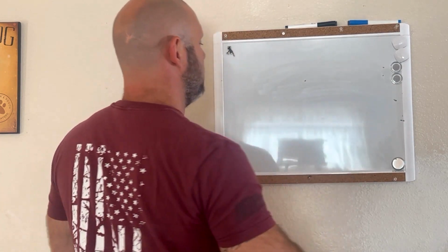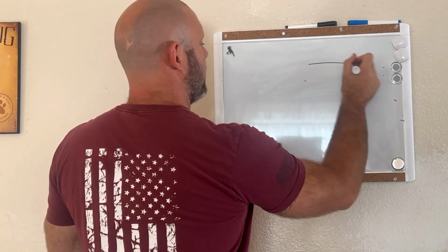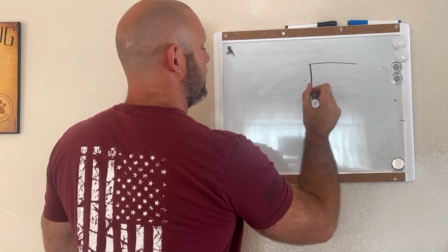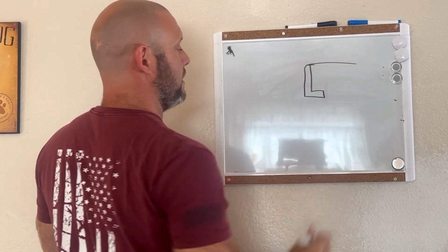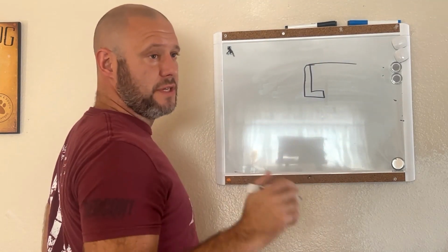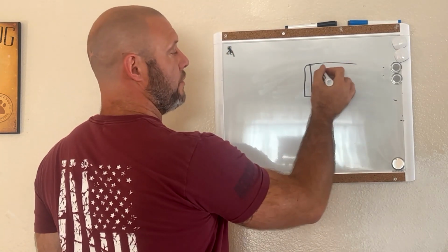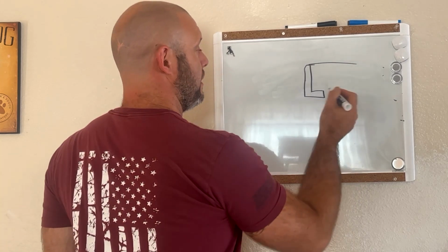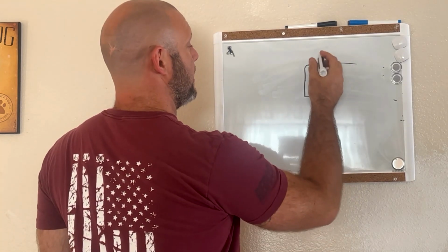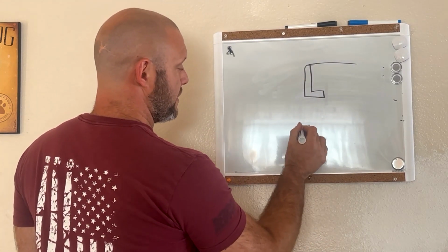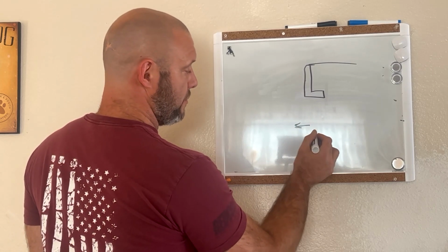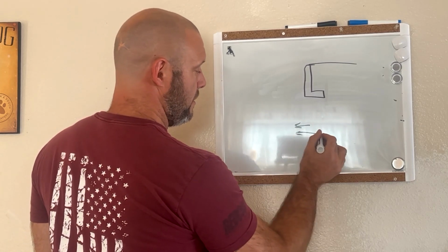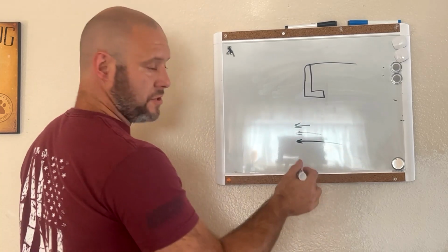So if I've got a hillside, right, I'm just going to put an L-shaped footing here like that. A couple things to note is that the shallower you are to the surface, the less the lateral forces are going to be pushing on the retaining wall, right? So if I were to represent the forces with an arrow, a short arrow is smaller forces, and then you'd have larger forces and larger forces, right?